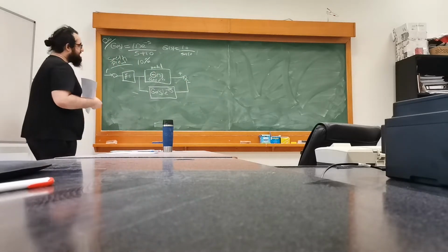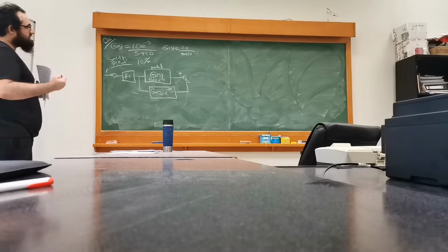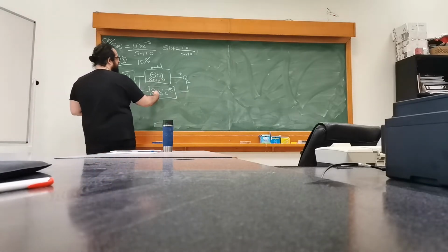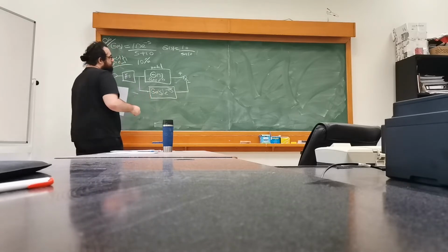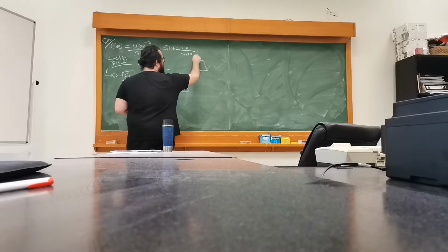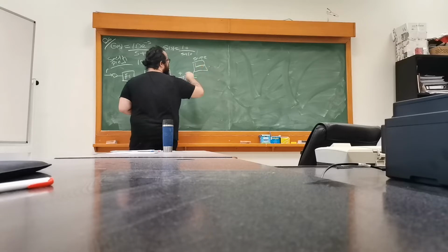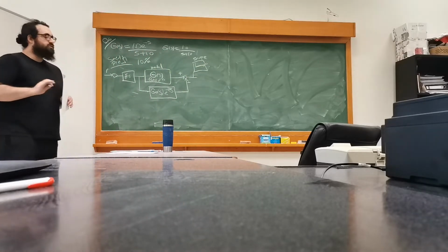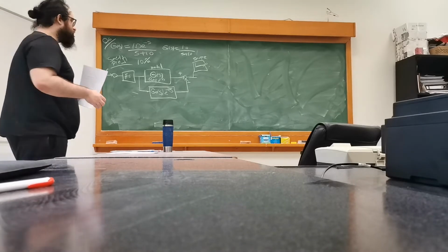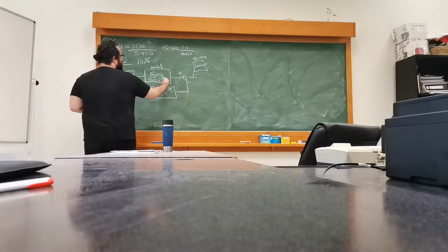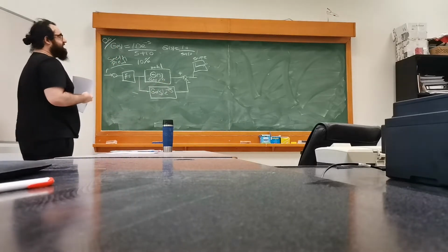And the reason for this is that this part tries to match the controller and match the system with this transfer function. If we connect a scope to this signal, it should give us 0 output. So basically, it should generate no difference at all in order to have a working Smith predictor. So this should predict the model, match the model as it is.